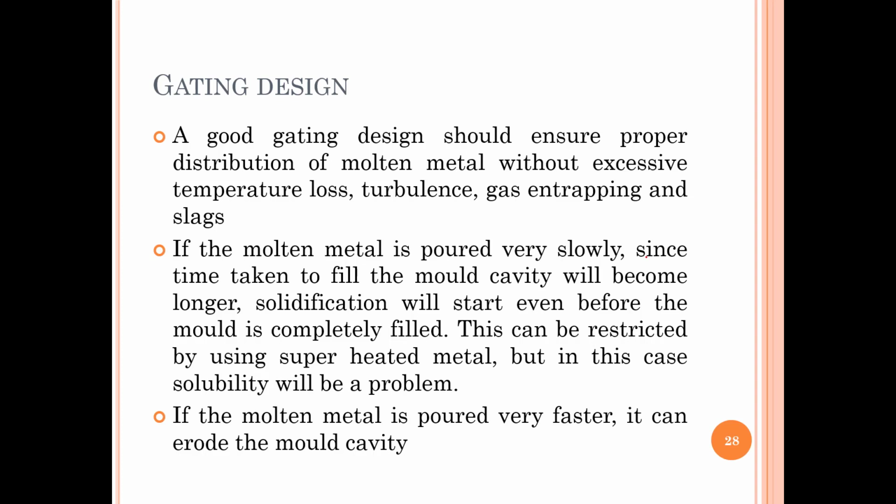Next, we are going to discuss the gating design. A good gating design should ensure proper distribution of molten metal without excessive temperature loss, turbulence, gas entrapping, and slag.